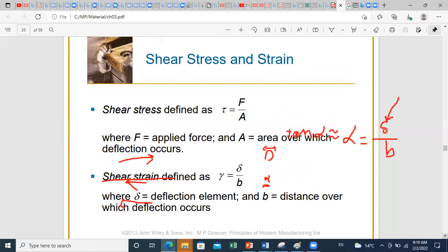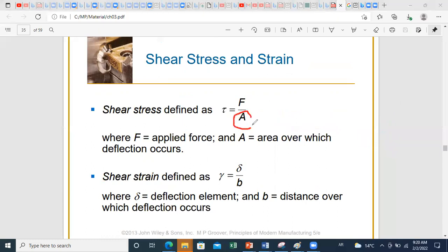So here, as we did for tension and compression, we define shear strain and shear stress. The shear stress is defined as the force applied over the cross-sectional area. Now, another difference between shear tests and tension and compression is that in shear you don't have a change in the cross-sectional area. So the cross-sectional area will not vary, but you will have a deformation in angles. So in shear you don't have two curves, you don't have engineering and true curves, because the area will not change.